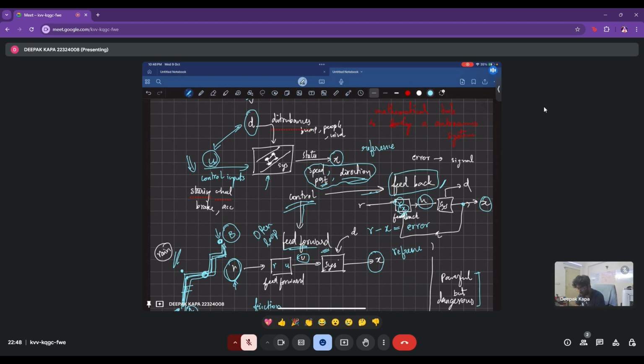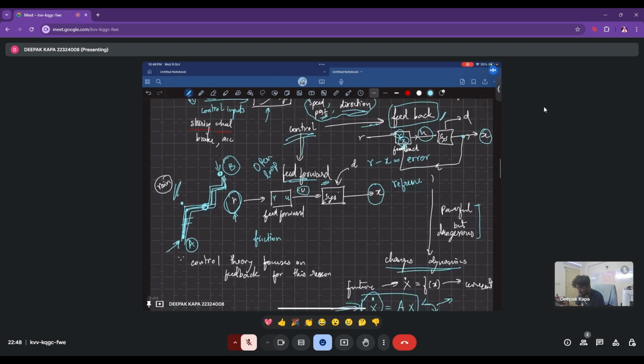One of the ways is called open loop control, and those controllers are often called feed forward controllers. Basically, a feed forward controller has essentially one input, called the reference variable. The reference variable is a variable that tells the system what we want it to do. Say I want to go from point A to B, so this goal would determine the reference variable, and based on this reference variable, the feed forward controller would generate a set of inputs that would be fed into the system at one go.